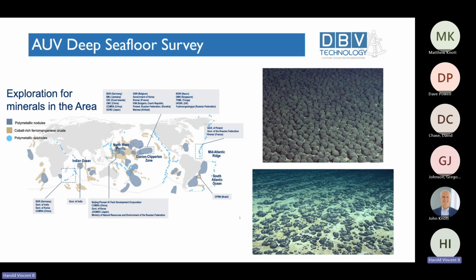And so you'll launch an AUV from the surface. That AUV now has to descend down to deep depths. So for example, in the Clarion-Clipperton zone, the CCZ, there's a high density of these nodules down there. And that's a water depth that's normally 4,500 meters, 5,000 meters deep. And so it takes several hours for an AUV to descend from the surface down to the bottom. It's incurring all that inertial navigation system error growth before it gets close enough for the DVL to get speed over ground and constrain the error growth.